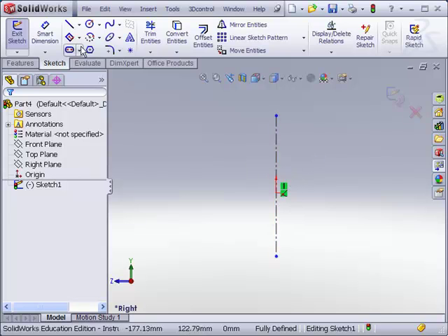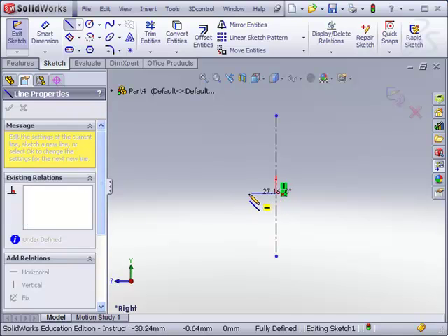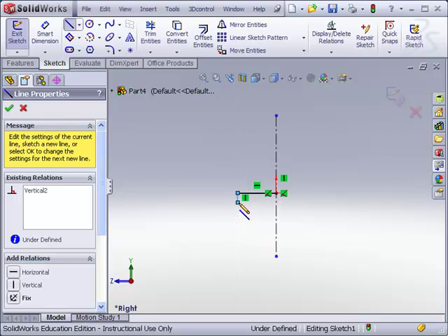I'm going to have it at the top. And I'll do that by starting a line. And I'm going to snap to the origin, go to the left, and I'm going to draw half of the part. That's why I have that center line in there. So the overall width of this axle support is 82 millimeters. So I'll go over to about 41 millimeters. Then I'm going to go down about 10 millimeters, come down at an angle,